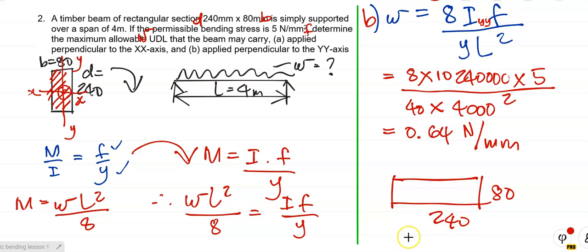That is why whenever we place a beam, we always place it so-called vertically. We place it with the deeper side vertically so it can carry more load that way as opposed to carrying load that way. So people, there's number 2 done,